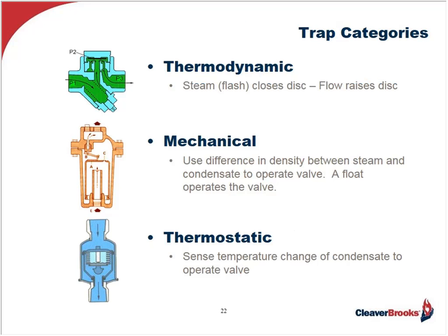And at the same time, the professional assessor will be looking for at least those steam traps which are readily visible and observing the types employed, because as you can see with this slide, they vary in design and in functioning. As such, specific types are employed depending on given applications. Some just work better than others given these specific conditions. The other thing about traps, which is important here, is that no matter what type is employed, they have three specific functions. They trap steam, they evacuate condensate, and they purge air.